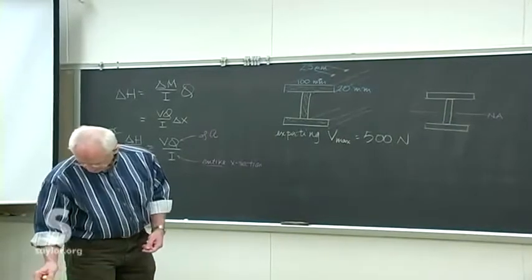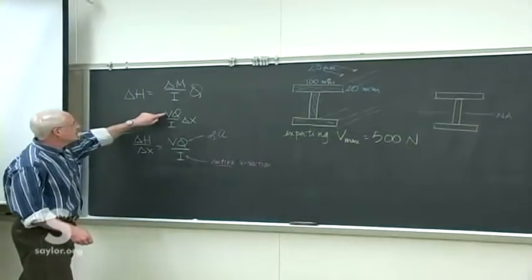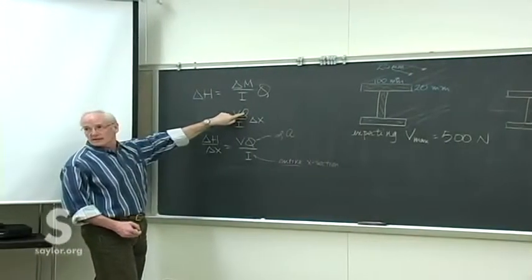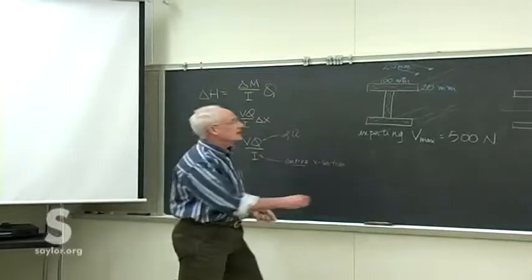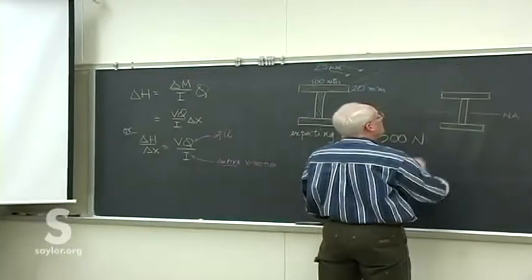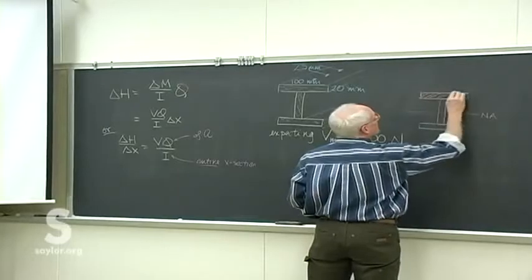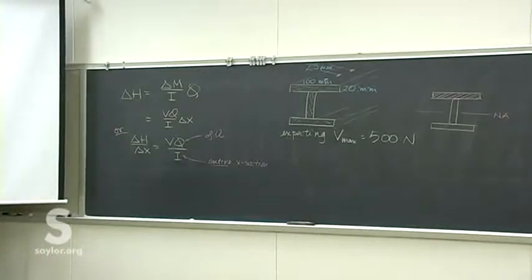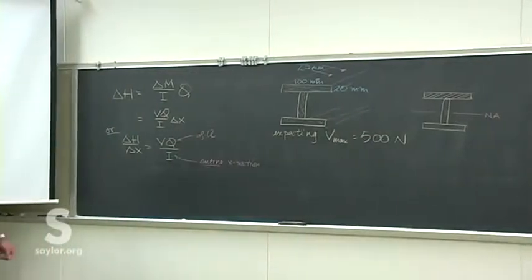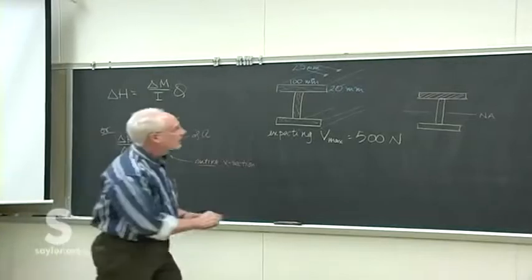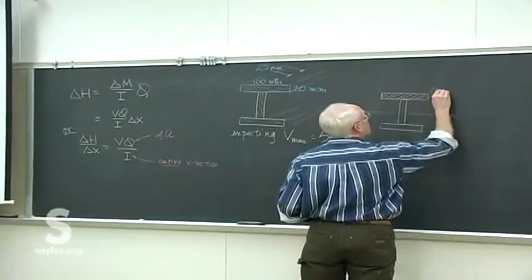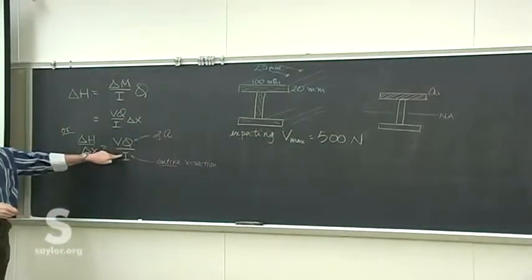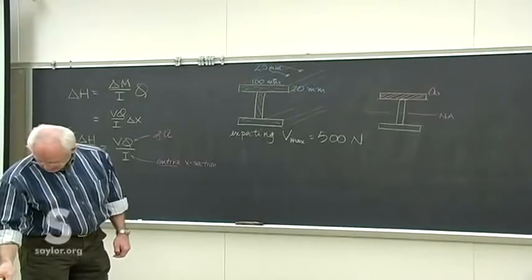All right, so we've got the shear. We need the Q, the first moment of area, with respect to the neutral axis of the part above the plane of interest, which is this entire area there. Not just the part of area directly above the intersection of those two planes, but the entire area all the way across. So that's our A. So we need the first moment of area of that. Then we also need the first moment of area of the entire cross-section.